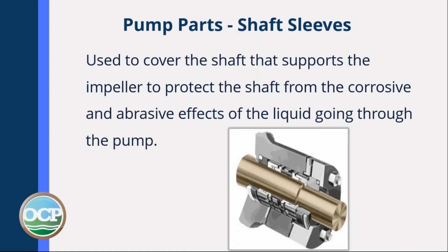Pump parts, you've got shaft sleeves. These are used to cover the shaft that supports the impeller to protect the shaft from the corrosive and abrasive effects of the liquid going through the pump.